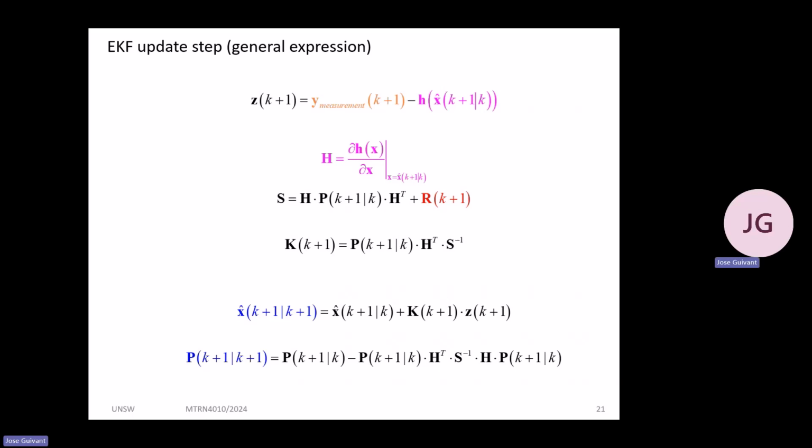All right. What else do we need in this expression, the capital H matrix? What is that? It is the Jacobian of the output equation with respect to the state vector, evaluating that Jacobian at the current expected value of the state vector. So this will produce a matrix of numbers. This is an analytical expression. It's a matrix with numbers. Okay, good. And H is going to participate in all this operation, in which it is very important to see we have the participation of the covariance of the noise polluting our measurement.